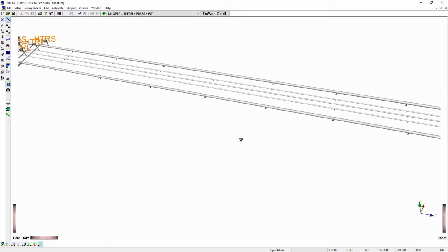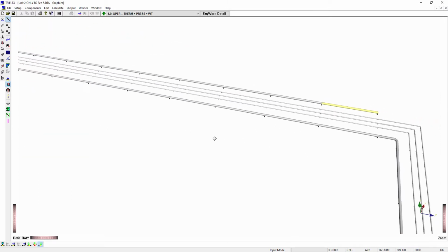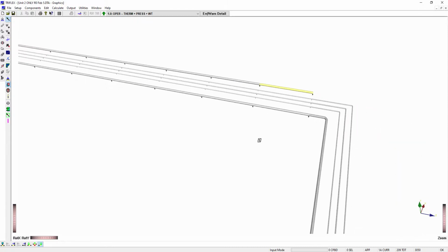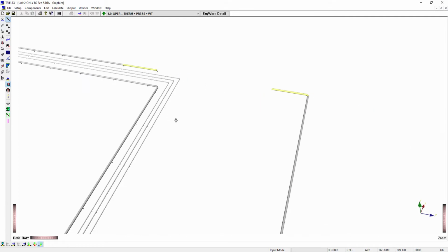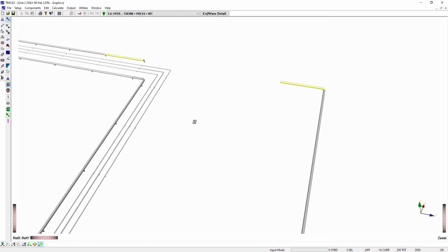And now, certainly because we offer several or as many as you want assigned locations, you can work yourself into a fix. If you assign 2 locations and you try to change a component length, for instance, in between the 2 locations, then TRIFLEX will give you an error. And we're gonna see one of those errors right now.